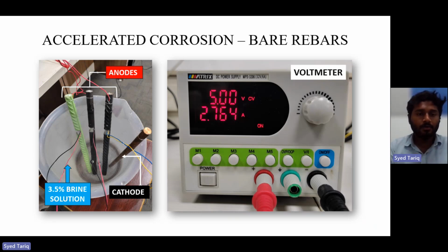Here we are making an electrolytic cell, because to accelerate the corrosion there should be a potential difference between the two materials for the electrolytic chemical cell reaction to happen. The three rebars which we are going to corrode act as the anode, and a copper bar acts as the cathode. The cathode is connected to the negative terminal of the voltmeter, and the three rebars which act as anode are connected to the positive terminal.